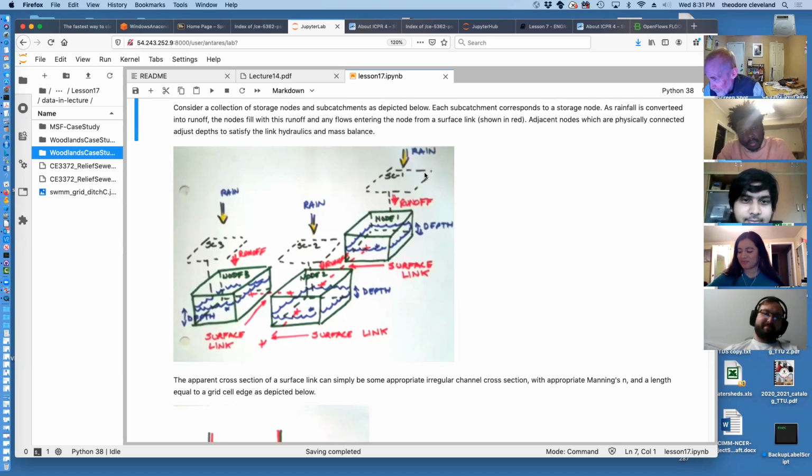So anyway, those particular, oh, and my favorite one, because it was the guy who heard a who, there's Horton's method and modified Horton's method. And then there's the Dunne, let's see, infiltration. There's the Dunne saturation excess method. So anyway, there's quite a few models in the literature that provide a mechanism for us to computationally determine what the anticipated runoff is from a unit of rainfall on a subcatchment.